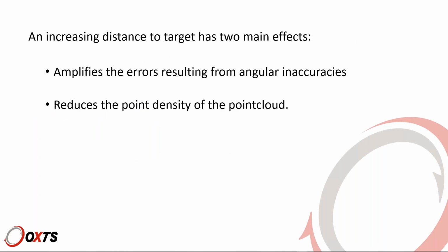It has basically 2 main effects. One we've already mentioned, and that is amplifying the errors resulting from angular inaccuracies. The other effect of distance is that at longer distances, you will have a reduced point density of the point cloud.